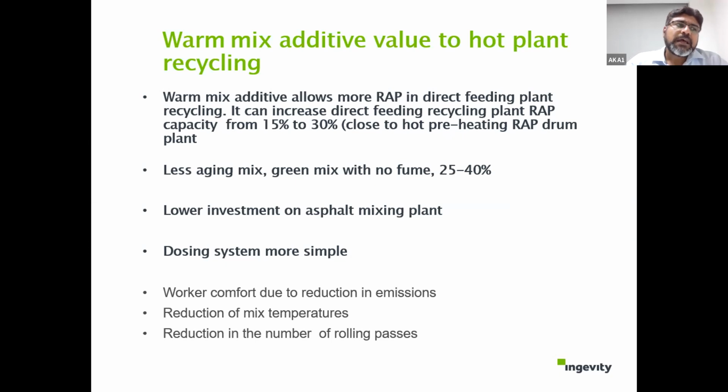And the second thing is, I would put it this way: the most vulnerable period any bitumen goes through is before construction. What I mean to say is, a bitumen is heated to 160 degrees only once in its lifetime, before it is constructed. Once the road is constructed, the bitumen is never going to touch beyond 60, 70 or anything. From the refinery till the plant, it would have been heated and reheated, and then while producing the mix, it's heated at 160.